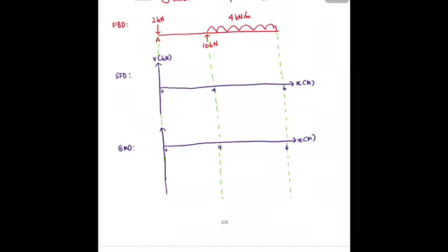If you refer to the free body diagram, you have 2 kilonewton downward. So from 0 until 2 kilonewton, negative 2 because it's downwards. Between AB, you don't have anything, so you go straight. Negative 2. And then at point B, you have 10 kilonewton upwards. Negative 2 plus 10 is equal to 8. And then you go up until 8. So this is 8.